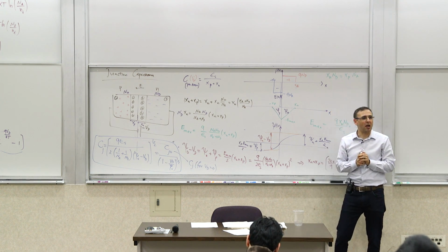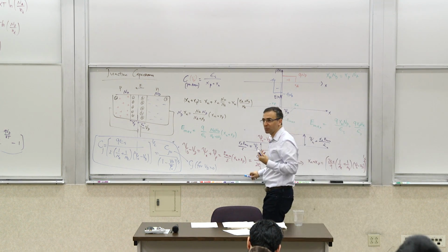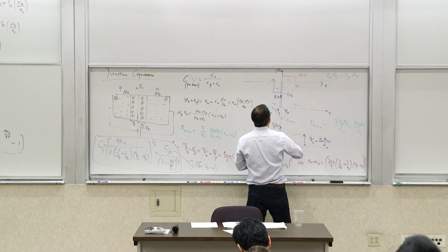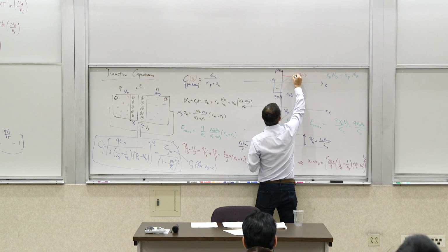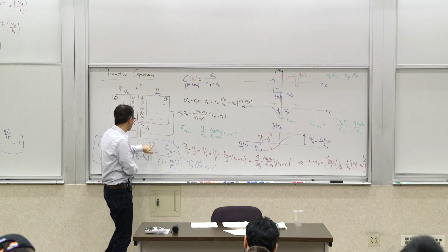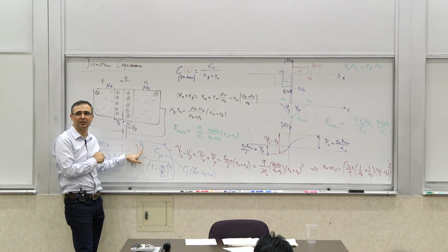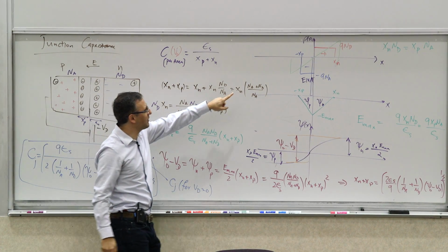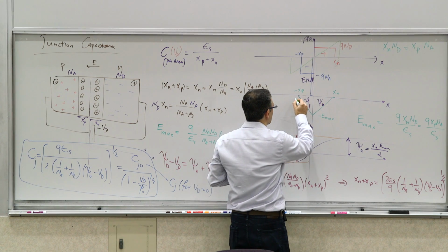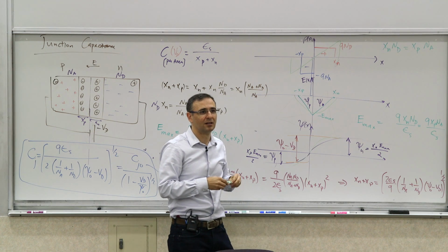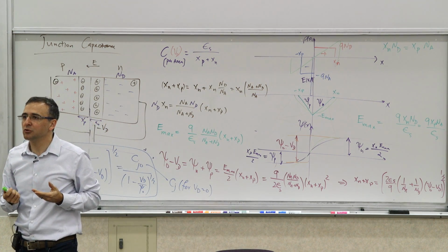So now, let's say I were to start with linear doping concentration as opposed to constant. So let's say my doping concentration looked like this. So it's called a linearly graded junction. Now, what would you say that this exponent would be? 1/3, right? Because you're starting with linear, you will get quadratic here, so this becomes quadratic, and then this becomes cubic, and therefore that becomes a cubic root.